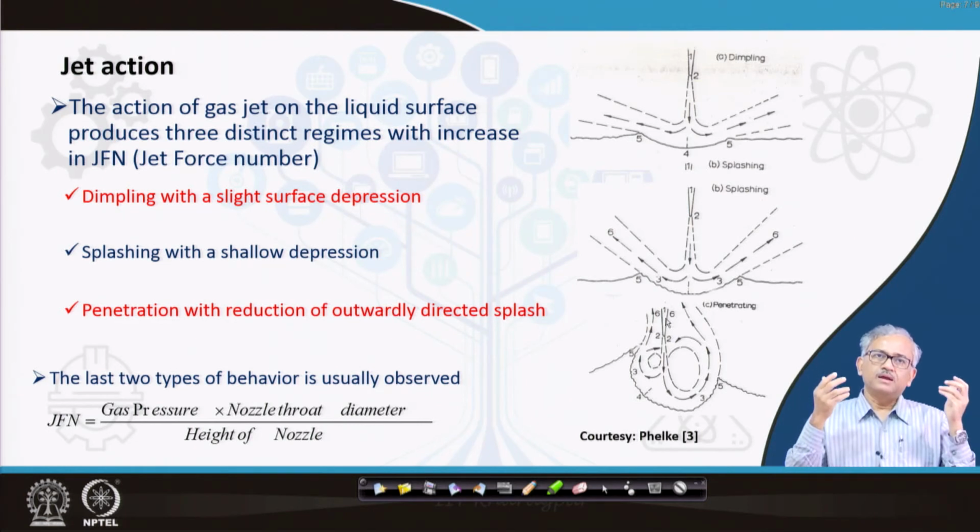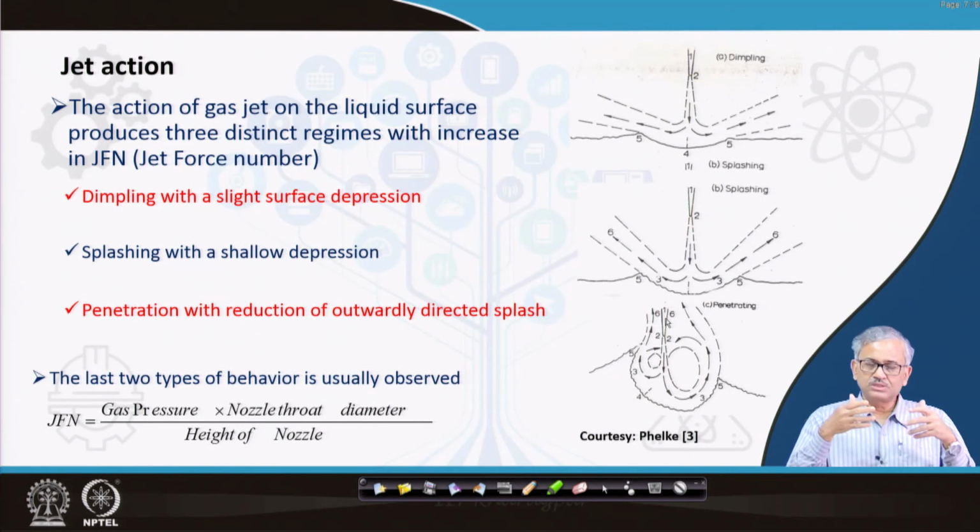Okay. And at the same time, you are generating the oxygen, that is, you are first oxidizing the iron also, you are generating the FeO also, and both decarburization and FeO formation are going on. But if your GFN is very high, then the case may come where the rate of decarburization is more compared to the rate of generation of FeO, because in that case oxygen can directly dissolve and react with carbon and directly form carbon monoxide, not necessarily through the FeO.